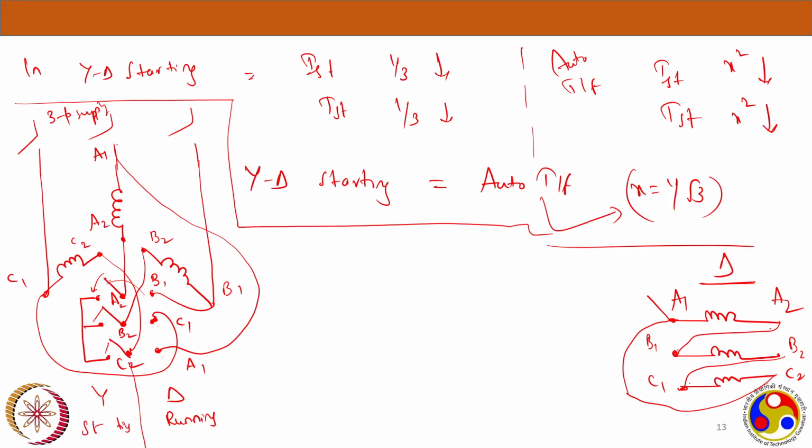This is a kind of lengthy problem, because we need to obtain slip at different torque conditions. But if you understand the concept and remember the formula, it will be easy to solve this particular problem. Let's see. We were given the Tmax at slip: the maximum torque occurs at slip equal to 0.16, and it is double the full load torque.